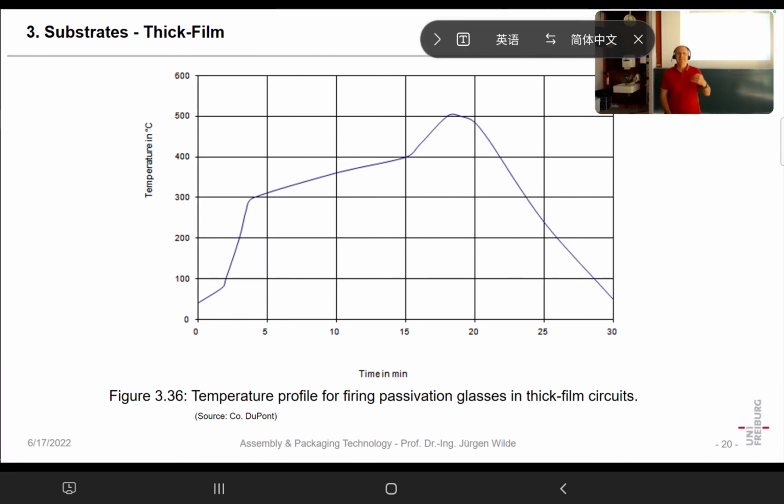It's more straightforward. I already said when you overheat such a resistor afterwards, it will change its value. And so going to 850 degrees centigrade again, it's like an additional sintering for that resistor alloy.